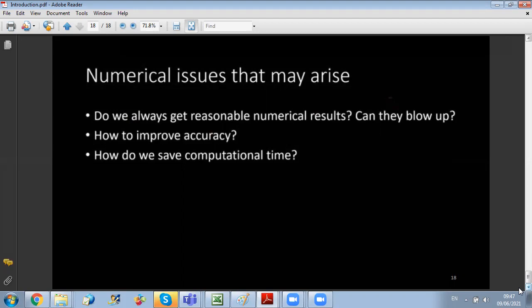For example, if you want to predict the air distribution resulting from an HVAC system, you can draw it in a CFD software, computational fluid dynamics software. You just give inputs. What is the velocity at the inlet? What is the temperature at the inlet? And how will the flow distribution be in the room? You can predict the flow distribution, the temperature distribution, etc. So you need to provide information about velocity boundary conditions and temperature boundary conditions.